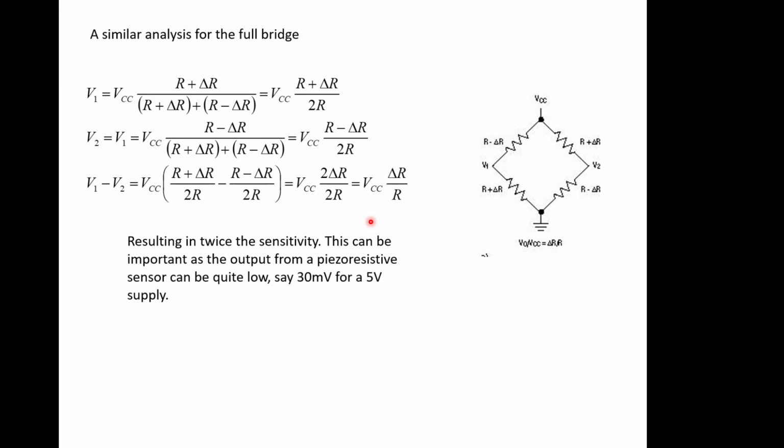So you can see how all this is coming together now, with an understanding of what a common mode and a differential signal is, and you can end up with a system that's very good at suppressing noise and amplifying a very small signal. The signal can be so small that you can't see it in the noise by eye on an oscilloscope, but such a measuring system is very good at extracting that signal, because we know the signal is differential and we know the noise is common mode.